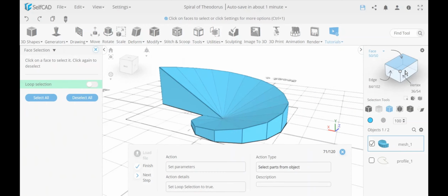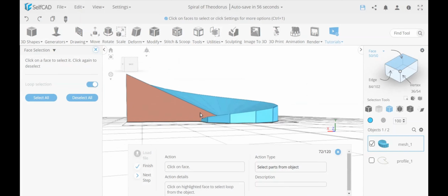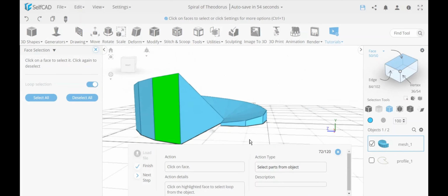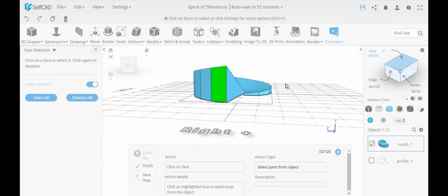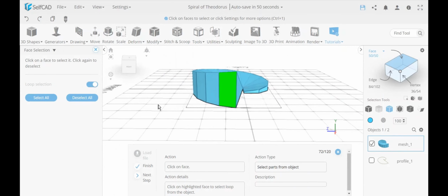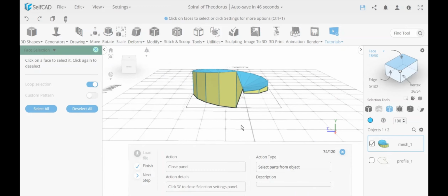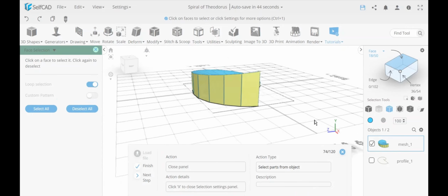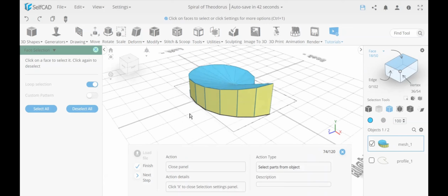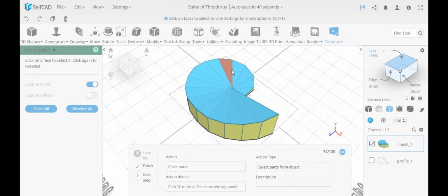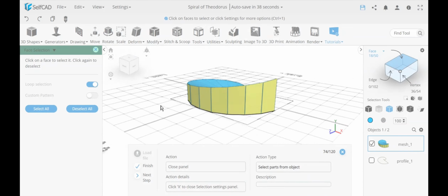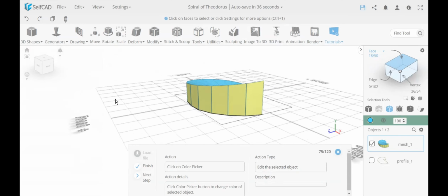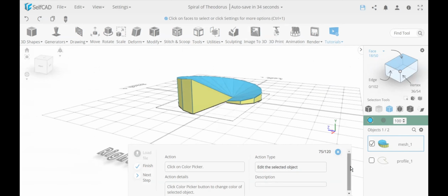And the tool we are using is, we open this advanced settings, the gear icon, and in that there's an option loop selection. And this again is a selection trick. How do I select the entire loop, the outside that I'm trying to do? And loop selection is something like this. I've shown it before. You click on one and then you click on its neighbor, and it magically selects the entire loop. And this can only work based on quads. So we have a quads. If you're going to try to loop select this, it's not going to work because these are triangles. So this is where we're going to take advantage of the material selection, as you see in a moment.